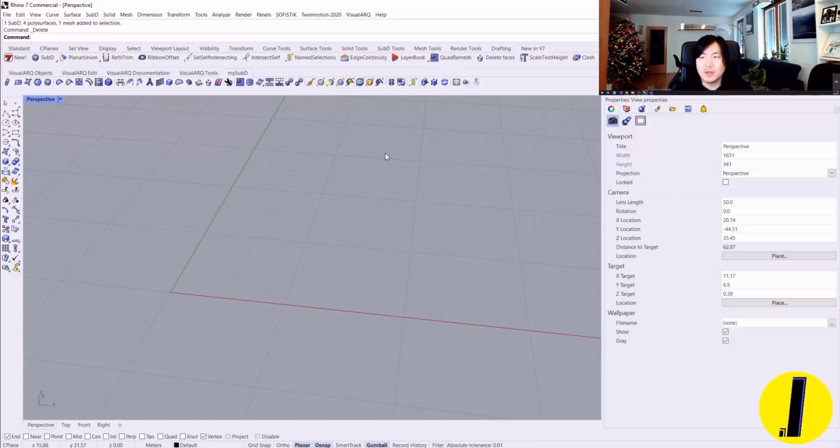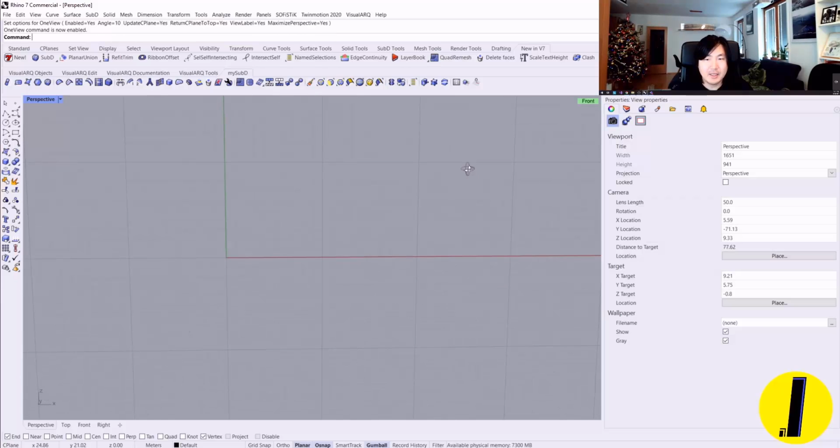There's a command called one view, and I brought it here, the icon single viewport mode. When your perspective view is aligned to the front view, your construction plane is aligned to the front view. Or if I move it, it's aligned to the top view, left view, or right view. This is really handy because now I'm going to draw some curve lines.